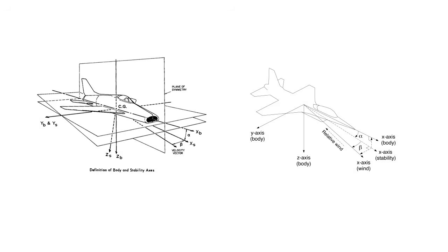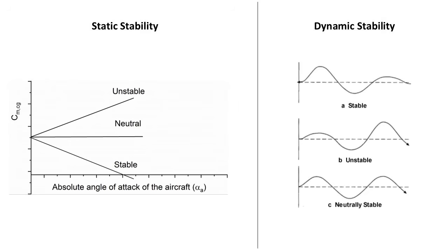In a broad sense, stability is just the tendency of a system to return to its equilibrium condition after being disturbed from that point. There are two main types of stability or instability that are important. First of all, static stability, and second of all, dynamic stability. An airplane must have a stable system with acceptable time constants, meaning in general we want the dynamics to be acceptable, but actually more than just stable, we need appropriate damping and frequency here.